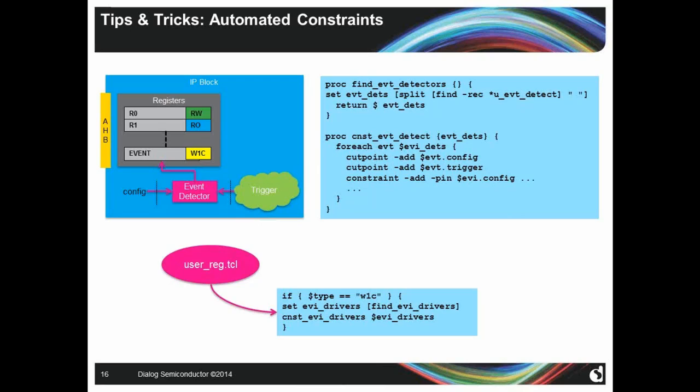So we have to place some constraints around that because it's configurable. We wished to make sure that we had cut points and place some register constraints around the inputs to that event generation logic, so that we could run these write one clear checks without being influenced by any other complex logic in the DUT. So it's cutting that away because that wasn't relevant to the check that we were trying to do.